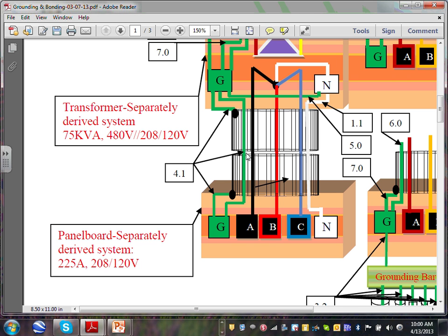the two enclosures together, inside the conduit or outside, right? Because we typically use a flex. That wire here is called the supply side bonding jumper. Does it sound familiar? That's exactly what we use at the service to bond the conduits. So you bond this enclosure to this enclosure through a wire that's called the supply side bonding jumper. Why supply side? Because it's on the supply side of the disconnect of the separately derived system.